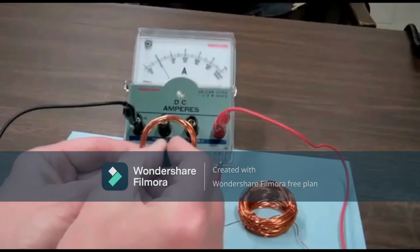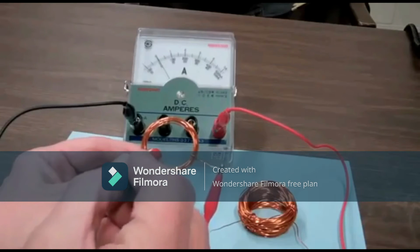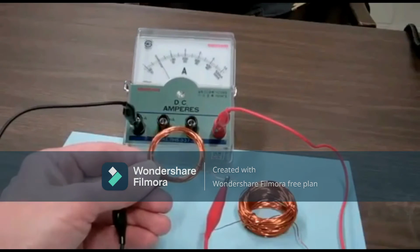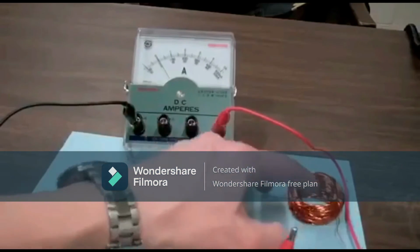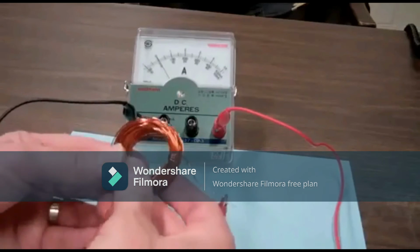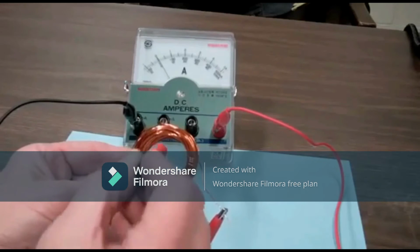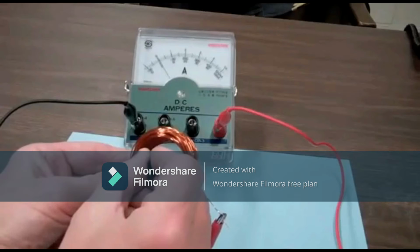And when the magnet is not moving, there's no deflection, indicating there's no current flowing. When the magnetic field is changing going into the coil, there's a positive current flowing. When it's changing coming out of the coil, there's a negative current flowing. And now let's connect the 100 loop coil and we'll start by moving the magnet very slowly. We'll see a deflection to the right and left, and if we go quickly, there's a greater deflection. So the rate of change of the magnetic field affects the current also.